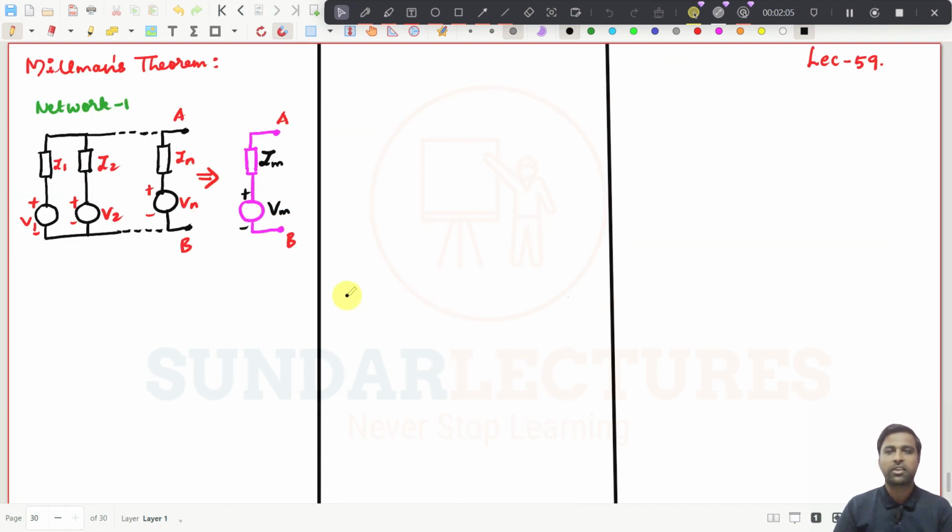So in this class we are going to see Millman's theorem. See, this is the network. For example, there are n number of branches, each with a voltage source in series with an impedance, connected in parallel like this. How can we do this? We can convert this whole network to a single voltage source and a single impedance connected in series across points A and B. The expressions for Vm and Zm will be the proof for Millman's theorem. That is what we are going to find now.